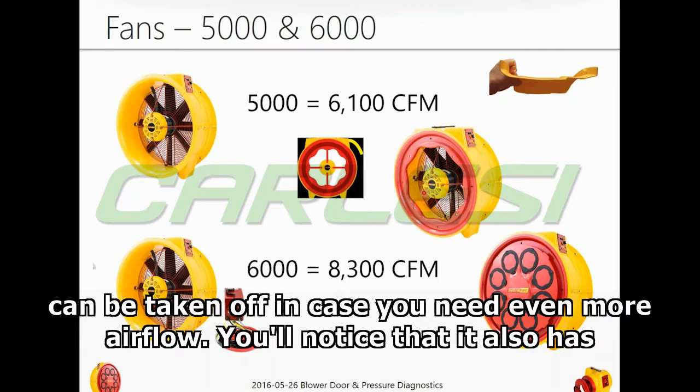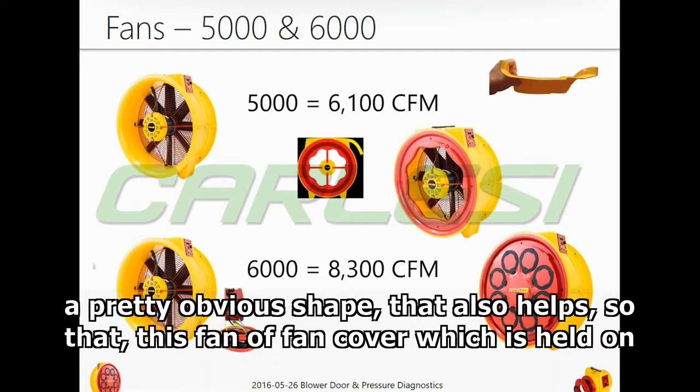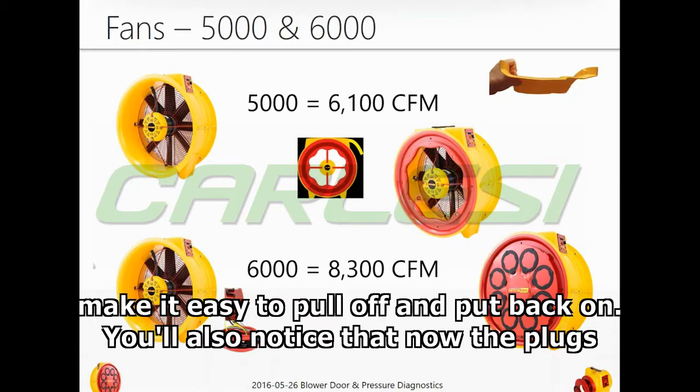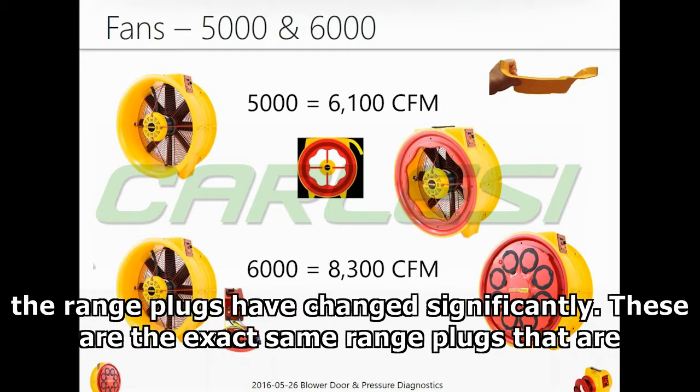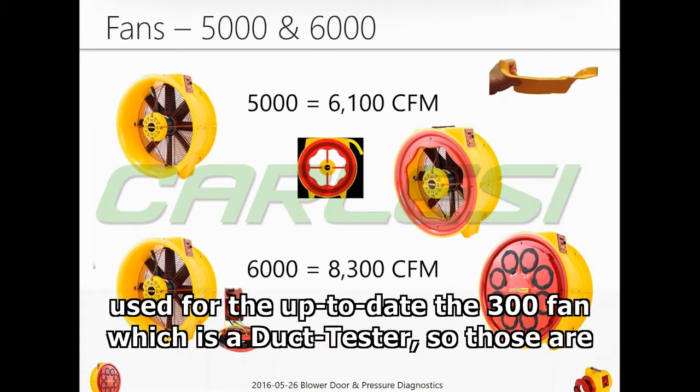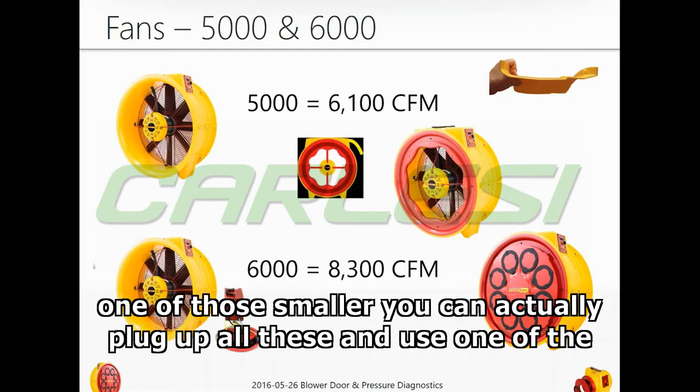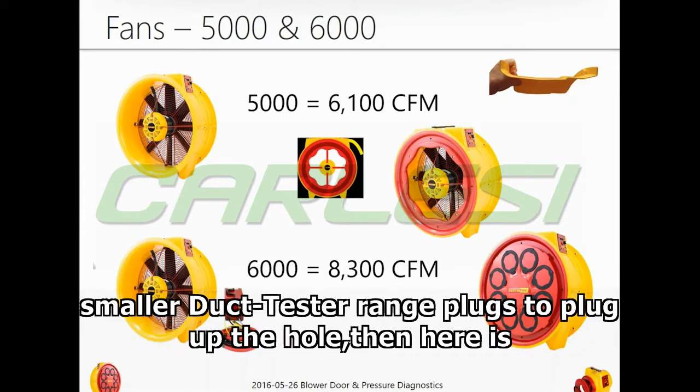You'll notice it also has a pretty obvious shape. The fan cover is held on with super magnets, which make it easy to pull off and put back on. You'll also notice that the range plugs have changed significantly. These are the exact same range plugs used for the up-to-date 300 fan, which is a duct tester, so those are interchangeable. If you're testing something very, very tight, you can plug up all these and use one of the smaller duct tester range plugs to plug up the hole.